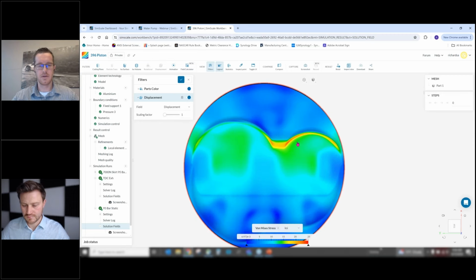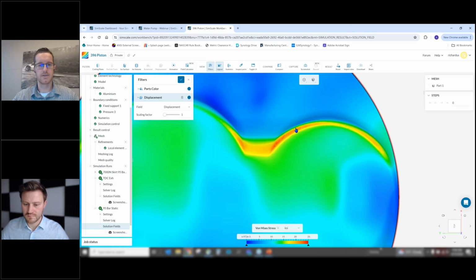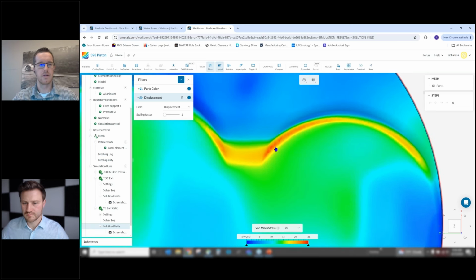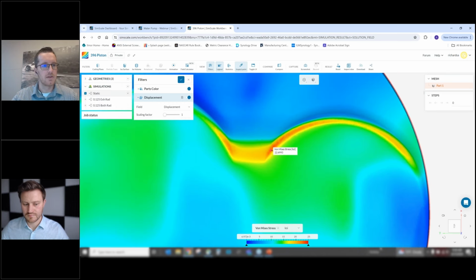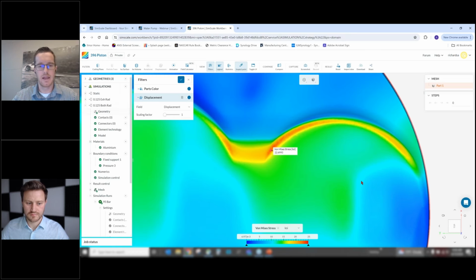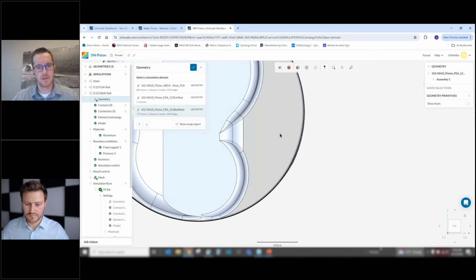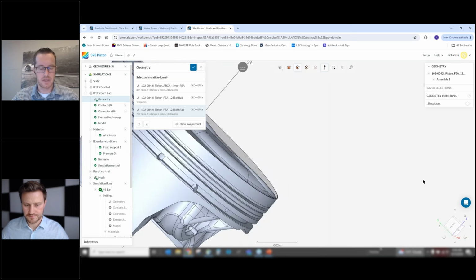So again, as shown in the PowerPoint, we identified these areas through here in the running samples, the samples that showed the cracks, as this is where the crack formed, and SimScale also predicted the highest stress in these same areas. So with that, we needed to develop some countermeasures, some updated geometry to combat that localized high stress area to reduce the likelihood of crack formation. That led us to an increased radius through that bit of geometry, effectively increasing the area.